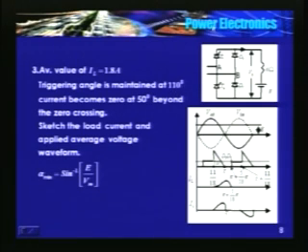So the load voltage V naught is the same as Vi from 110 degrees to pi, it is Vm sin omega t. From pi to 230 degrees, or pi plus 5 by 18 pi, the freewheeling diodes are conducting now.